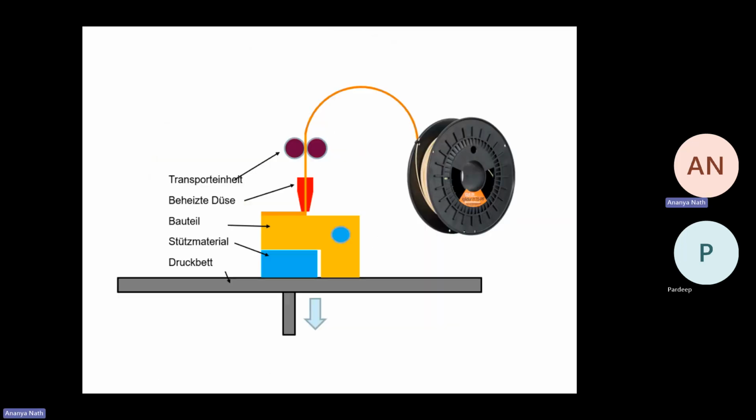Here we can print polymer or metal on different machines. For polymer, we use the induction heating, but for metal, we use resistance heating. It's just that for metal, you need more energy. And the raw material doesn't get fully melted, but is in a semi-melted form.